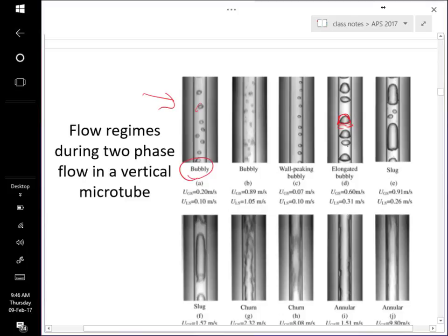And then once they reach the side, the bubbles can move as a piston through the tube. And so this is now a larger bubble there, and this is a slug flow because you're having pockets of gas and pockets of slugs, a region where it's almost all gas, and then a region where it's almost all liquid, progressing along.